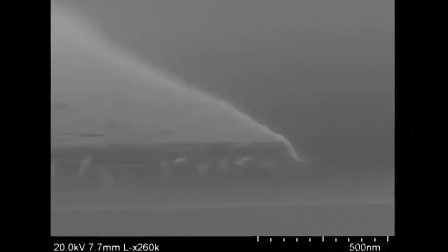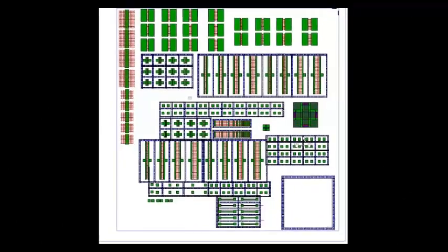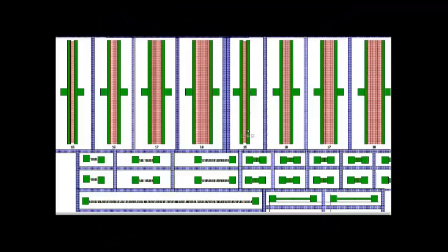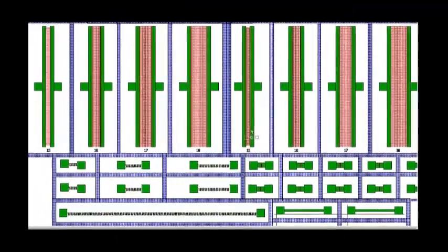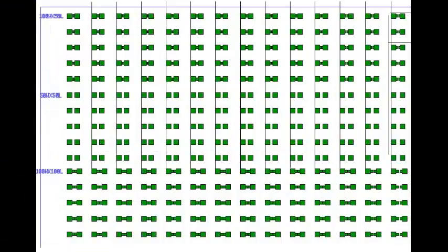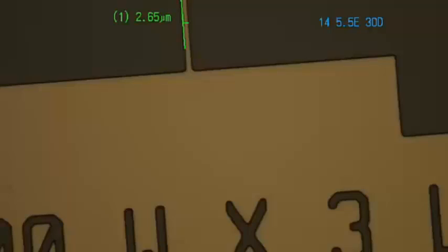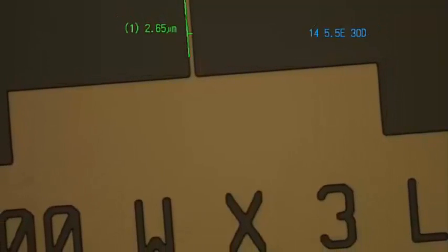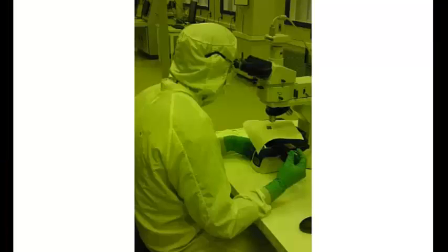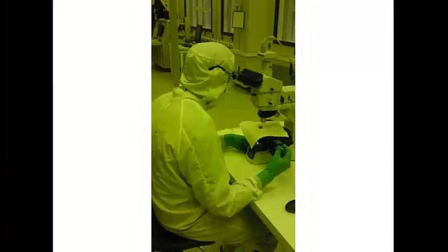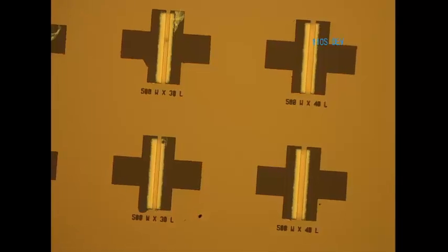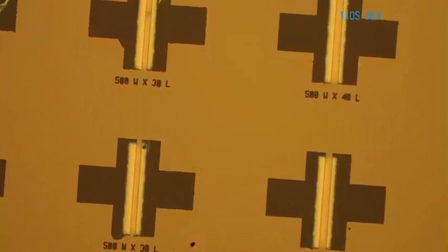I designed the patterns on the mask to accurately define where the metal and semiconductor layers would be deposited. I also experimented with various processes to increase the accuracy of our patterns. Due to the microscopic size of our critical features, which were only 3 microns wide, the patterning needed to be very exact. I worked with different chemicals and played around with different processes to increase the accuracy of our patterns, all to ensure that our smallest size features would be resolved.